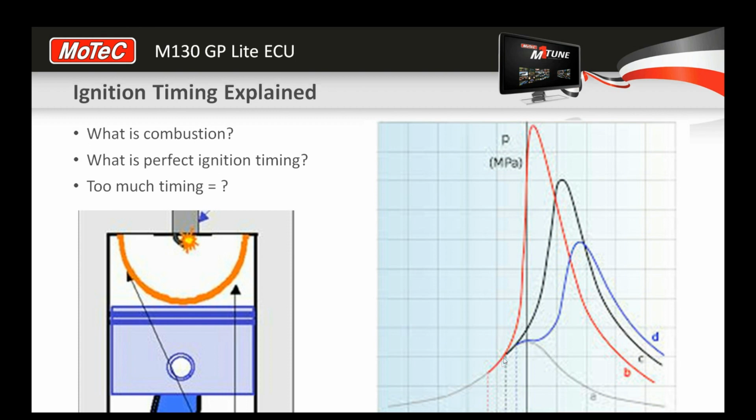The grey curve that you can see here is the cylinder pressure rise where there has been no ignition. The key is not turned on, but the engine's been wound over, so that's your compression pressure from simply cranking the engine over. Then we've got 3 different ignition points, where the cylinder pressure rises differently depending on when we actually put the spark into the engine.